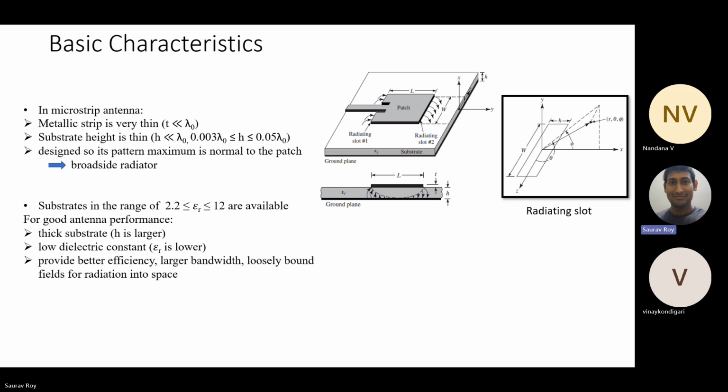Now, do you understand what I'm talking about? Sir, but entirely it is the same thickness. Now, why is it slot one and slot two? Slot 1 and 2 have been specially mentioned because they are the radiating parts. There are a total of 4 slots at 4 sides, right? Out of that, only these 2 slots will lead to radiation, or will act as radiators for the antenna. The other slots will not. That we'll look into later.